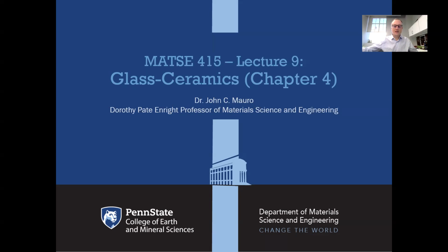As we know, most glasses are chemically homogeneous and therefore lack a microstructure. But what we learned last time is that it may be thermodynamically favorable in some cases for the glass-forming liquid to exhibit liquid-liquid phase separation, which could lead to spinodal decomposition or droplet nucleation and growth, in which case there are actually two liquid phases that give us two different glassy phases that have a certain type of microstructure, either this droplet and matrix type of microstructure or the interpenetrating phases of spinodal decomposition.